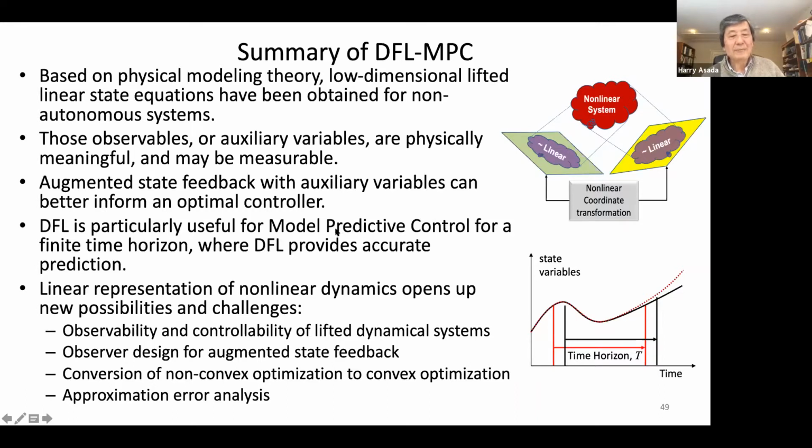There are lots of related issues, challenges and open questions identified. So, has anyone thought about the lifting dynamics? It may make you a little bit uncomfortable as to observability and controllability. Controllability is definitely not maintained, because it's basically bound by algebraic relations, right? So we cannot maintain the controllability. But fortunately, optimal control does not require controllability, so that's good for applying this to MPC. And observability is a very critical requirement. Oftentimes it is difficult to measure both the independent state variables and auxiliary variables, observables, at the same time.